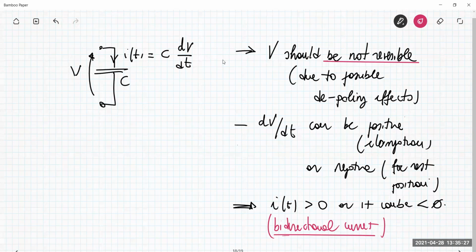What I'm trying to explain to you here is that drivers are better when they are in switching mode operation, when you are using reactive elements and switches in order to reduce the dissipated power and to increase the efficiency of the system. So what I'm searching for here is not to develop something linear. You can find integrated circuits that include linear power operational amplifiers for driving piezo actuators. But now I want to describe something in the switch mode operating mode. My power processing unit for this piezo actuator should be switch mode operating.